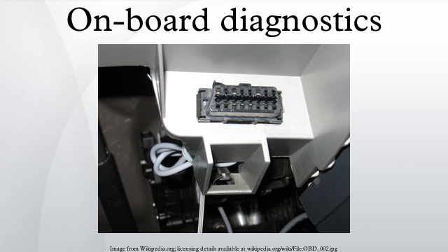For instance, on the Corvette there are interfaces for the Class 2 serial data stream from the PCM, the CCM diagnostic terminal, the radio data stream, the airbag system, the selective ride control system, the low tire pressure warning system, and the passive keyless entry system. OBD 1.5 has also been used on Mitsubishi cars of 95-97 vintage, some 1995 Volkswagen VR6s, Buick Riviera of 1995 vintage and in the Ford Scorpio since 95.